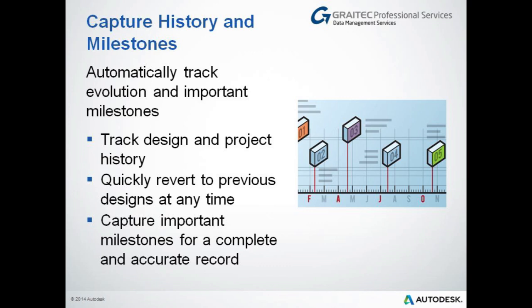And I guess really, if you're starting out, you may want to make use of this by using the version history and having milestones. So even though it's not technically a revision, you can capture milestones in the design and comment those as you go through. Every time you check in, a version is created. When you get to a key check-in, add a comment that suggests that it's a release level.